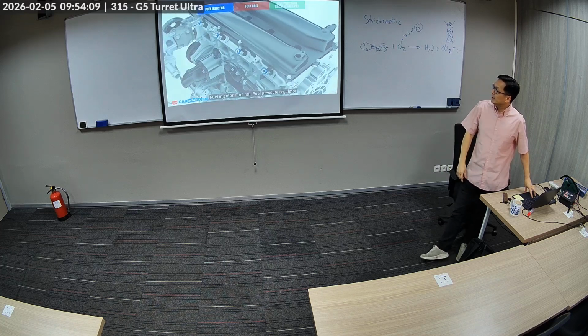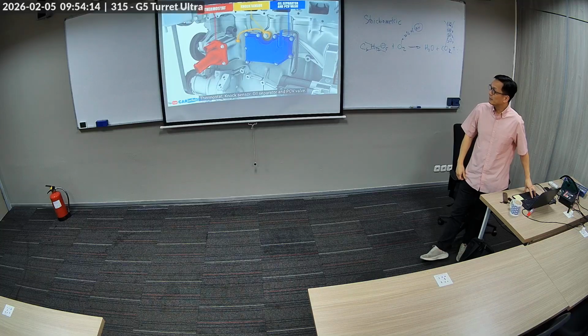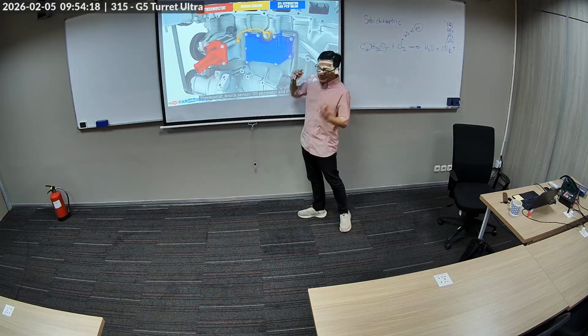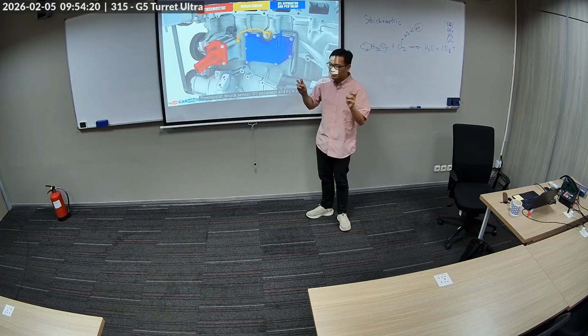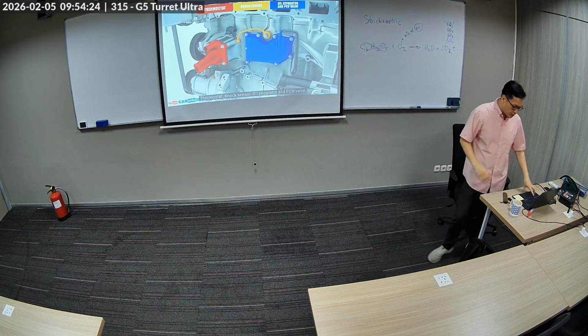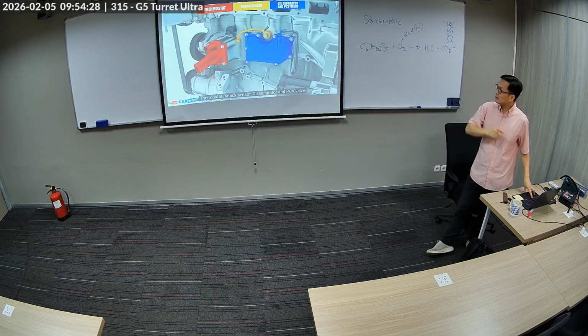So that's a fuel rail. For diesel engines, it's very high pressure fuel. So the knock sensor detects, it's basically a microphone. It's a microphone to listen to your engines, and it's tuned for a specific frequency. That's how it detects it. There's a thermostat. We'll talk more about that.